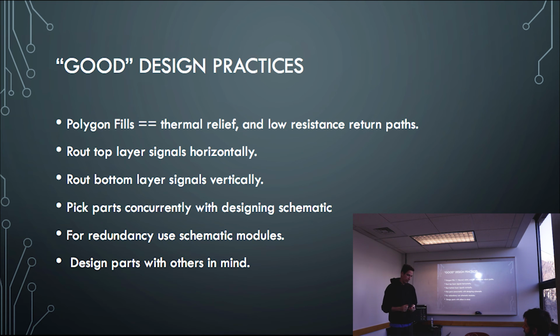Let's see. I kind of have a question. Yeah, go for it. So, how cluttered does it get before you make that decision to jump up to a 4-layer? Like, how much can you impede your ground plane before you're like, there's too much going on in my ground plane, I need to bump this up to a 4-layer?